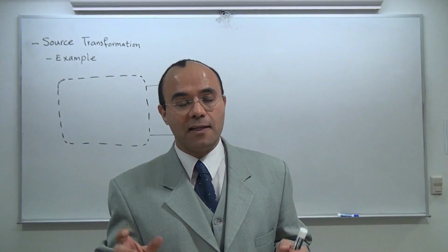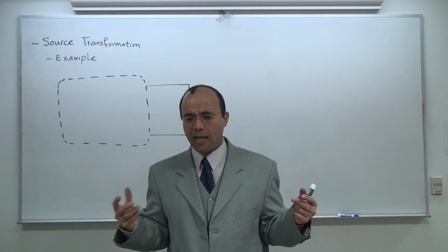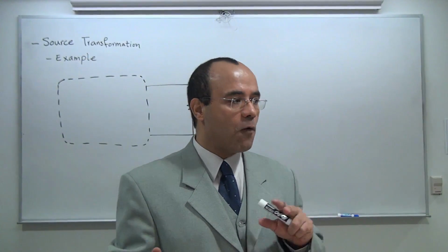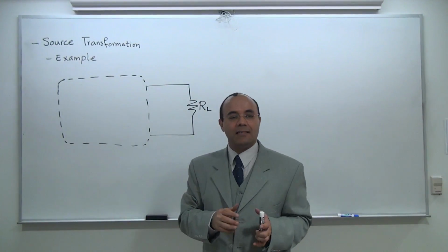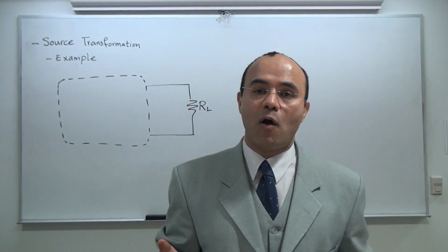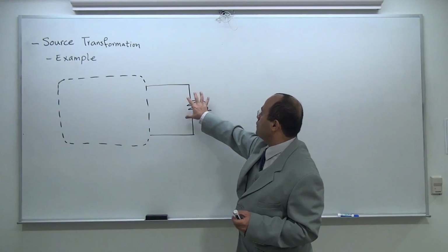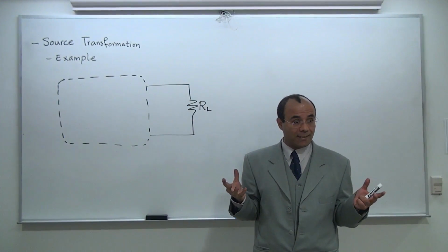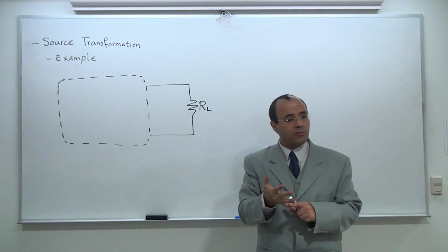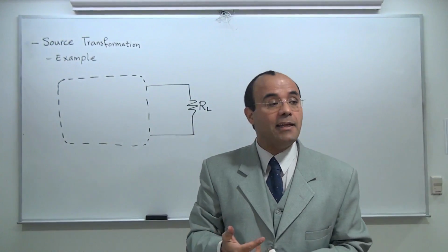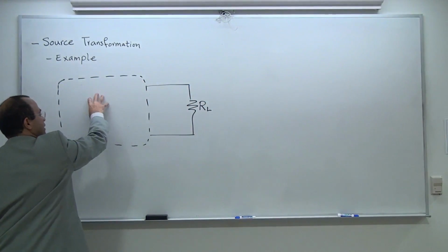50 ohm is a very typical useful value, kind of a standard, and everybody is trying to have the input impedance of whatever device they have set as 50 ohm, because as we are going to discuss later in Thevenin and Norton, it's going to provide the maximum power transfer to the design that you want to have. So the load, we would like to see how the load is going to be at the end of the 50 ohm, but before that, I have a typical load. This load can be short, which means zero, and it could be infinity, which means open. This load is actually imposing itself on the design.